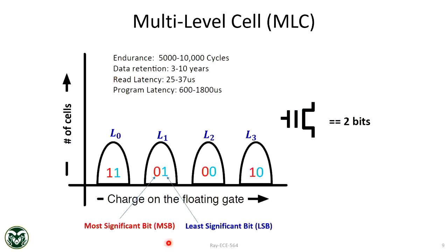Okay, so now let's look at how multi-level cell works. So this is your multi-level cell. You have 4 distinct VT levels, right? So you are storing 11, 10, 01, 00. This is gray encoding, right? So you are storing 2 bits. That means one cell can have 2 bits, in all those 4 states. We call them the L0 state, L1, L2, L3. These are the programming levels, L0 close to 0, then close to 2, 4, 6 volt. That's how we bin the threshold voltage, and we can apply references, right?